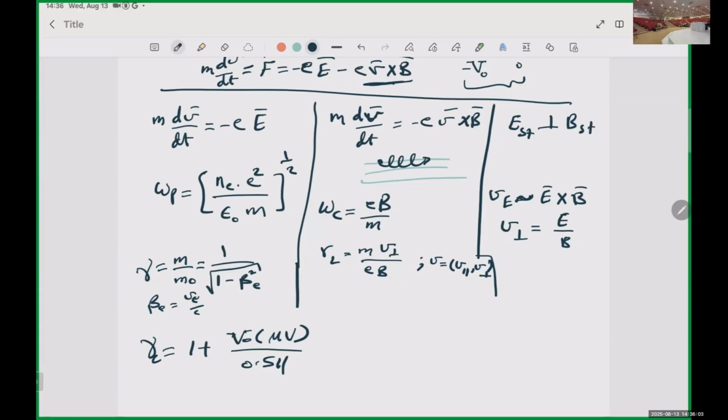Once the electron leaves the cathode and goes into the bounded structure, it will suffer from what they call voltage depression, so gamma will be reduced by some delta gamma. But this is so much complication that you don't want to worry about at the beginning of studying this field. You just want to assume your electron gamma is close to the cathode gamma.